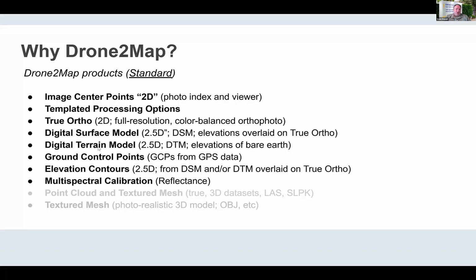It subtracts objects above ground level using thresholding, like the steepness of the side of a house or a tree, to create a theoretical ground level elevation model. Just as a side note, this works pretty well sometimes, not always. You can subtract the digital terrain model from the digital surface model in your GIS to get a canopy height model using raster math.